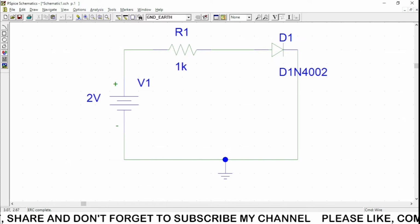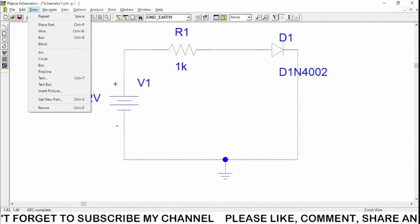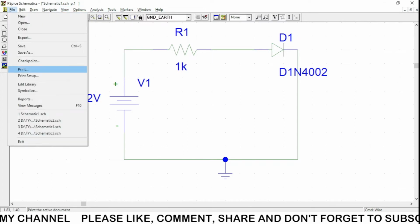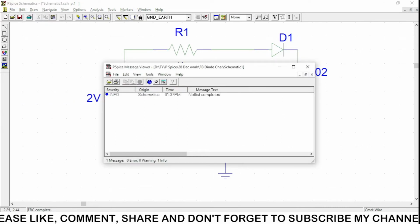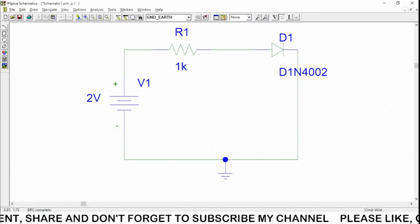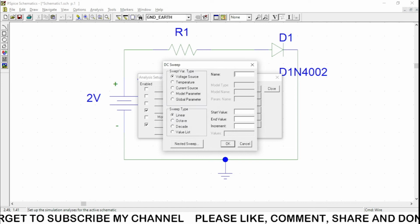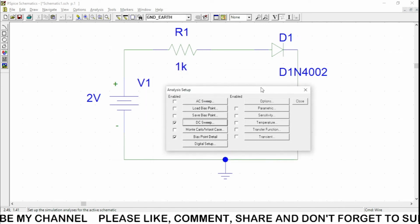You can see in a file view message, or by pressing F10, you will have one message, and that has zero error, zero warning. Netlist is completed. Then we are going for the next part, that is called the setup, where we are going to take a DC setup, as we are going to vary the voltage source. So what is the name of that voltage source? Let me take a look, this is V1.